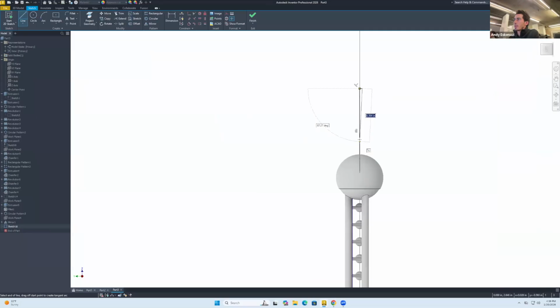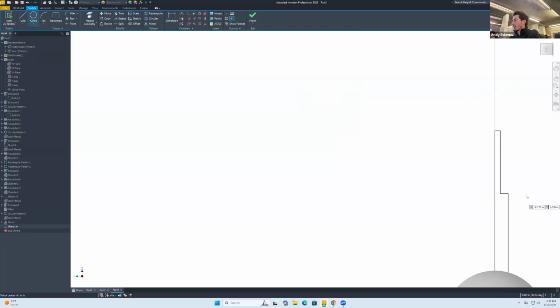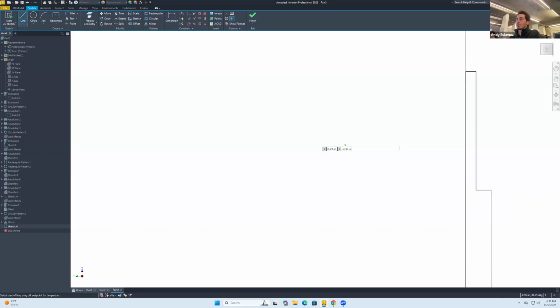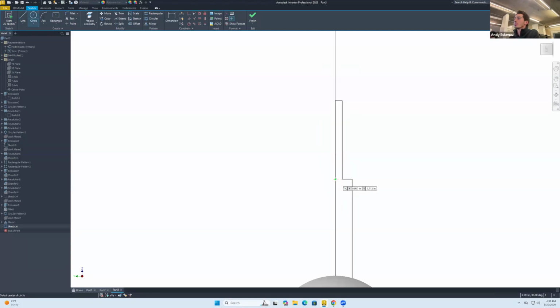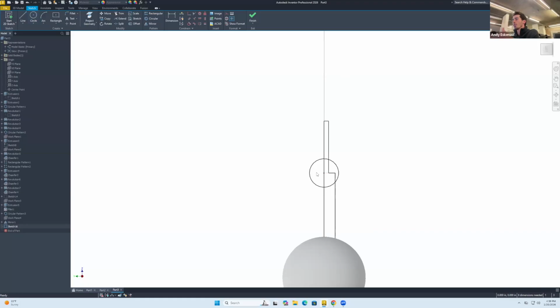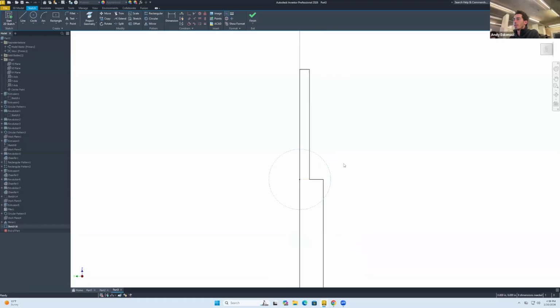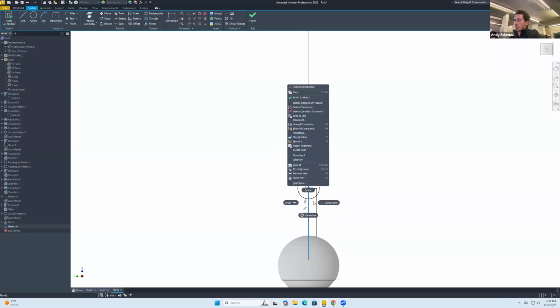And it seems that it's like this up to that point, and then it just stretches a little bit more, and around this area right there, we can put a circle. There we go. So I'll make that a construction. We're gonna add it around there, and then we're gonna obviously make a revolve of this thing. Let me do a construction of this stuff.